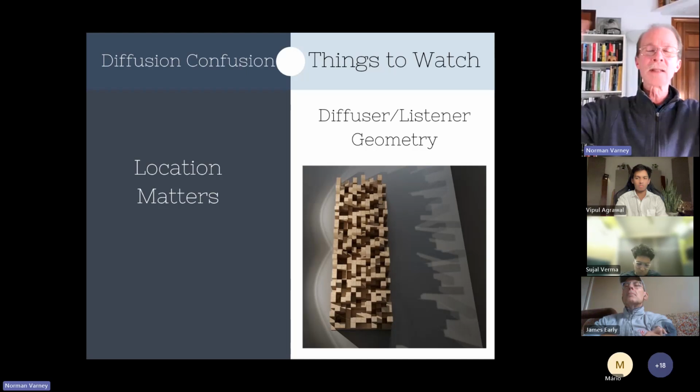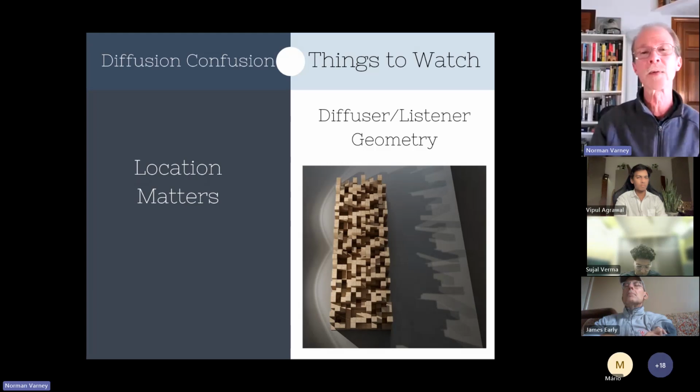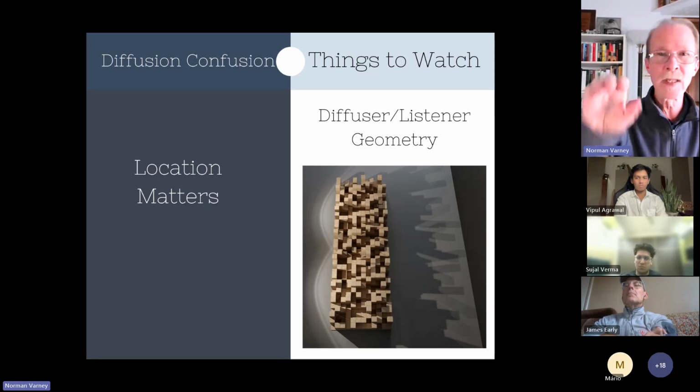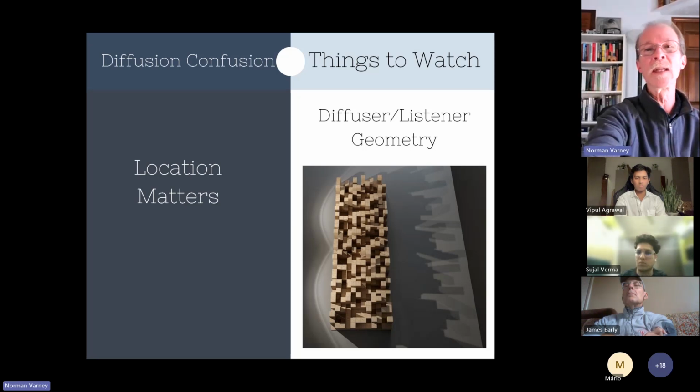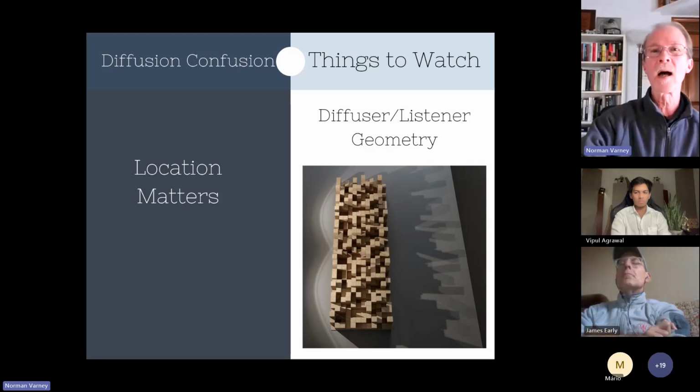Look how the high frequencies are pretty directional, so it's ray acoustics, and it works very much like light. They end up casting a shadow on themselves. Sound doesn't impinge into those wells and then reflect and come back out. It's blocked.